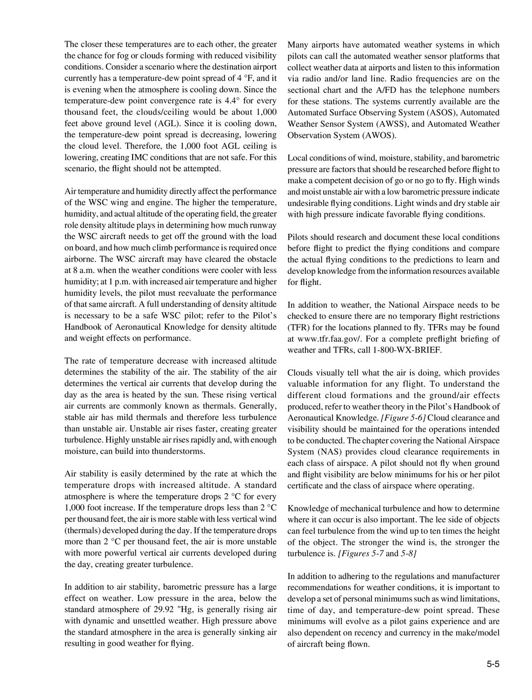The chapter covering the National Airspace System, NAS, provides cloud clearance requirements in each class of airspace. A pilot should not fly when ground and flight visibility are below minimums for his or her pilot certificate and the class of airspace where operating.